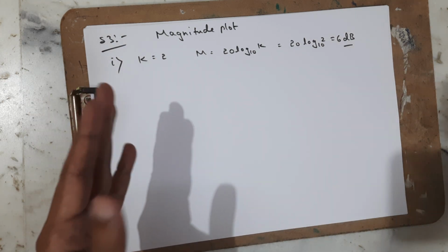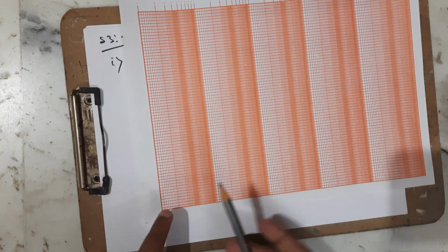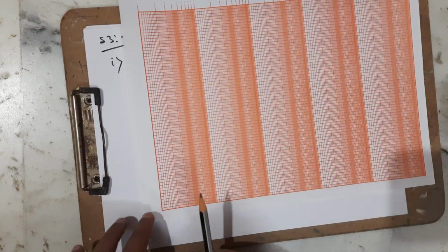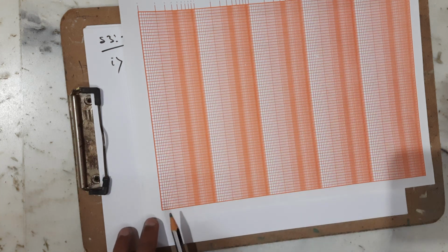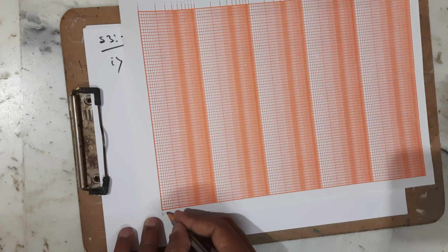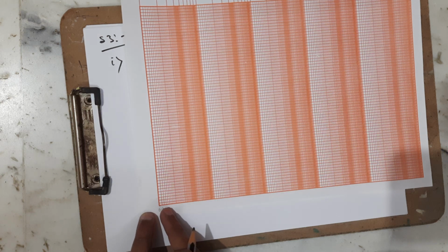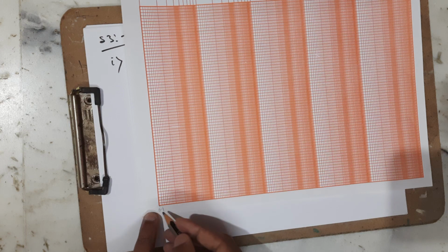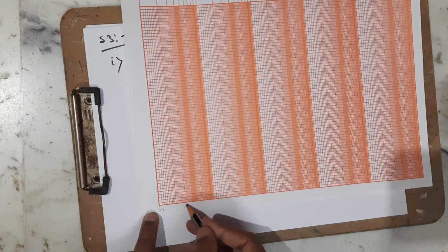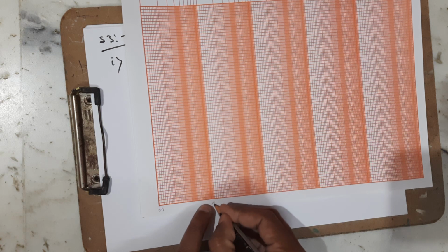semi-logarithmic sheet. So this is a semi-logarithmic sheet. Now I would like to explain how to represent the various factors. See, this is going to start with the smallest value, that is 0.1. Next it is going to vary 0.1, 2, 3, 4, 5 like this, and it will end at 1 radians per second.